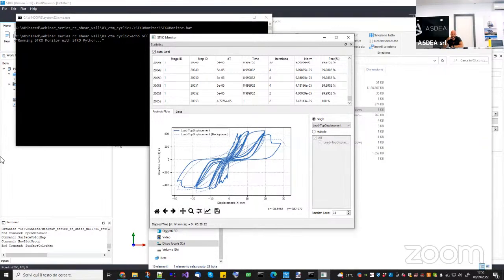Now, the problem with the hysteresis loop is, and I'm talking from a programming point of view, not a theoretical point of view, because in theory you can do anything you want. From a programming point of view, it's easy in a 1D model to keep in mind: my last point on the positive side was this one, then I unloaded, I'm here, now I'm unloading, I'm pointing toward this point.